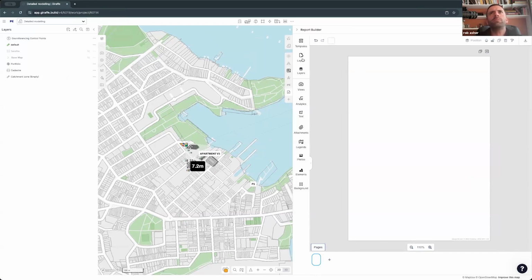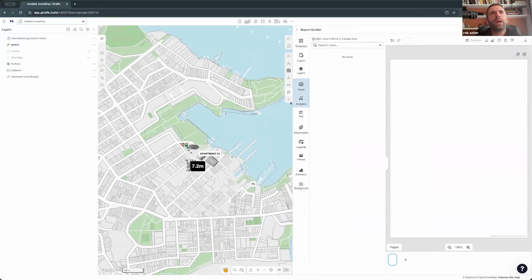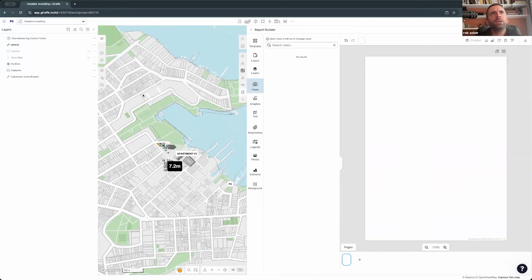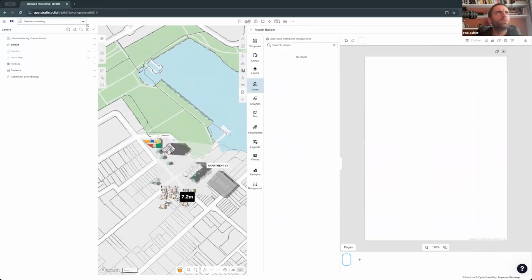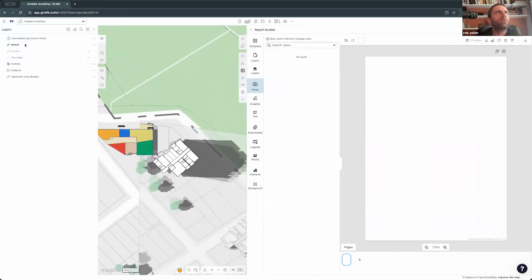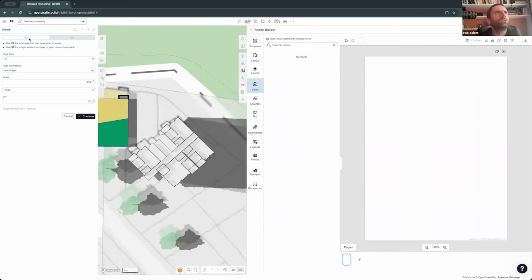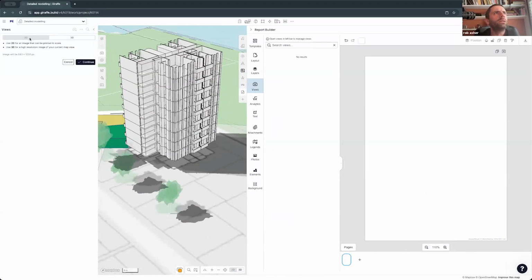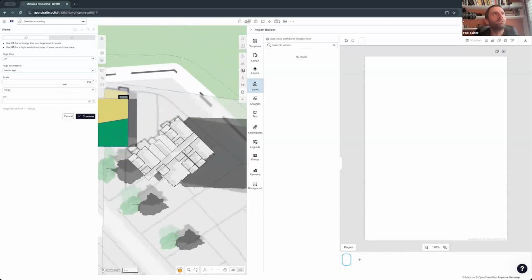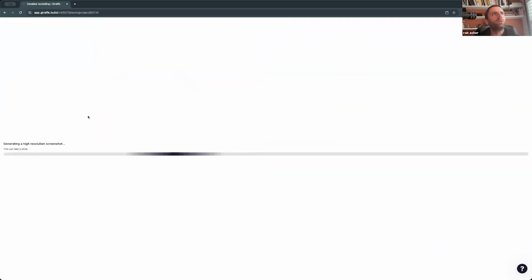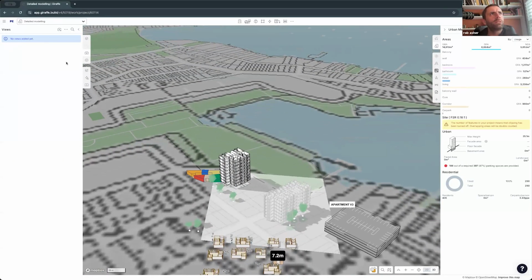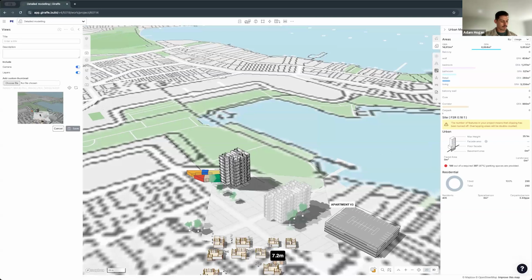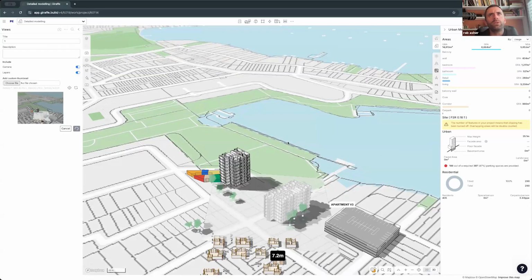You can also set the pages up, use templates, but what it has is access to the views. And so if you create a view, the way you create a view is zoom in as you want, click on the Views tab, click Add New View, choose 2D or 3D, so we'll choose 2D, choose a scale, DPI, etc., and continue, and that generates this high res. I won't debug this live, but if you get the view and save it, I'm not sure what's happening with the 2D view there.